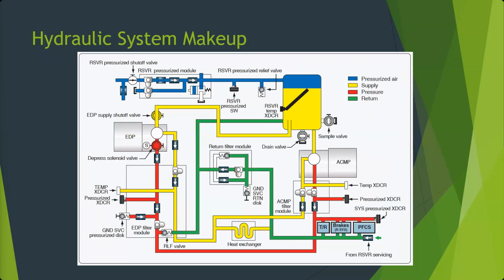So this is the fluid that goes into the areas that it's not actually being pressurized by the pump, it's going into the surrounding case, and it's providing lubrication. It's also going to be what carries away heat, providing cooling. Your main source of heat in a hydraulic system is not the things you're moving, it's the pump that's creating pressure, right? When we increase pressure, we're going to increase heat. And there's also friction that increases heat. The actuators don't really get that warm, but this is going to take the heat from the pumps, and that's why it goes through a heat exchanger before returning to the return side and back to the reservoir.